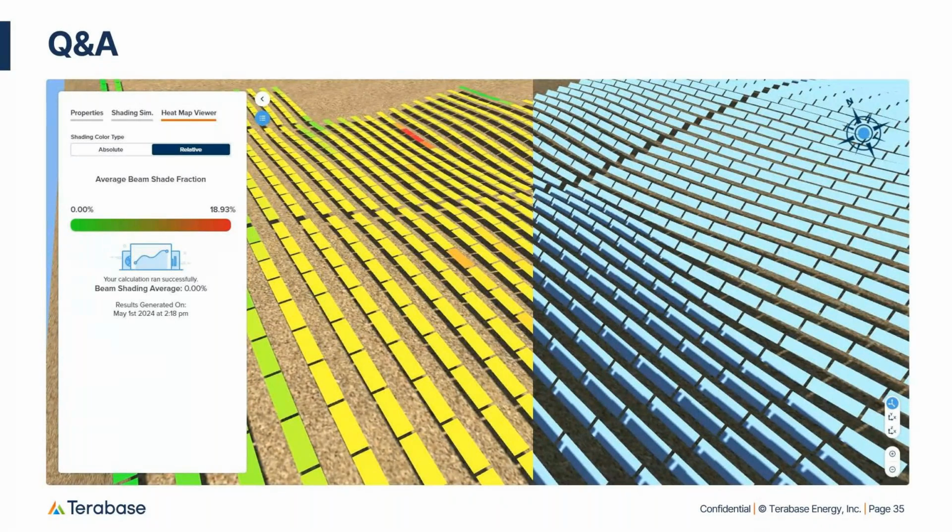Maybe one last question for you, Kurt. If you could speak to what the rear shading view factor is compared to other categories. On the rear side, we basically take the system definition. In PVsyst, you have your orientations and your 3D shade scene, and they're completely separate.